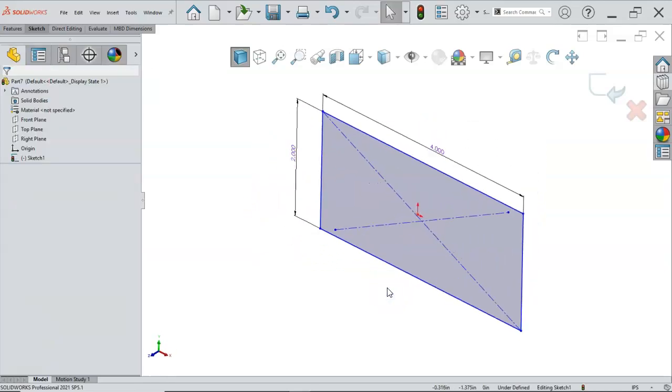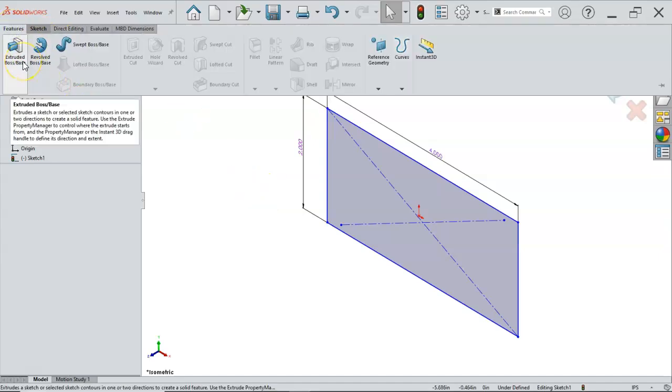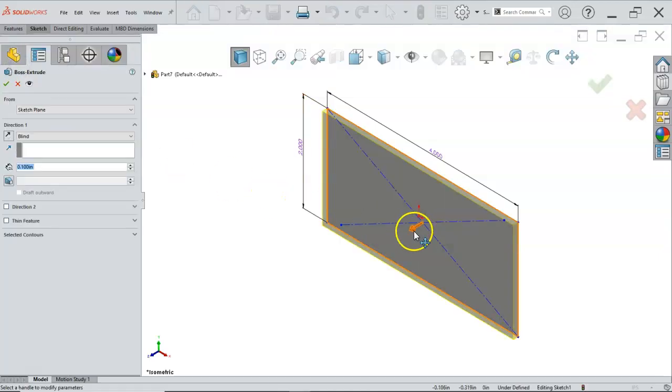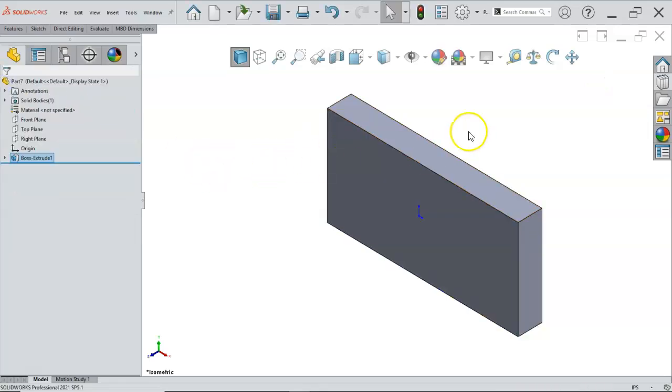And for an assembly, I would want this to be an actual part that I could insert and have it represent the stock. So I'm going to go ahead and extrude this out, have it go the direction that I think I want anyway. Usually I'm going to place this on the top of the part and have the geometry go in and cover up the part to represent the material that I picked to start with.